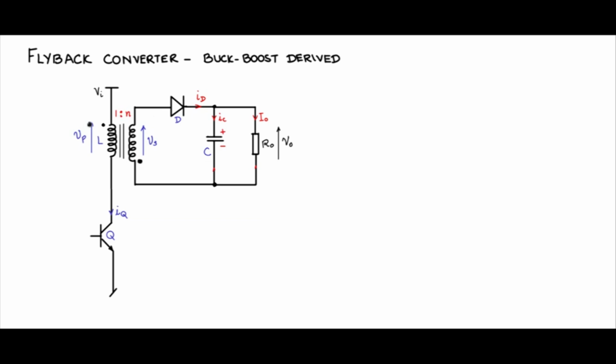Now, in order to understand this circuit, this is the complete isolated buck boost converter, also called the flyback converter, very popularly called the flyback converter. And look at the simplicity of it. You have one switch, you have one magnetic core operating like an inductor, and you have one diode and one capacitor. Simplest, least number of component count, and that is why it is so popular.